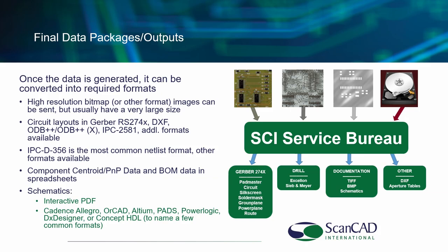And typically for netlist, we'll export IPC D356. It's an ASCII or a text-based file. For component pick and place data and bill of materials, we leave those in spreadsheets. And for schematics, we create an interactive PDF as well as Cadence Allegro. We're able to work in OrCAD, DX Designer, and other proprietary formats.